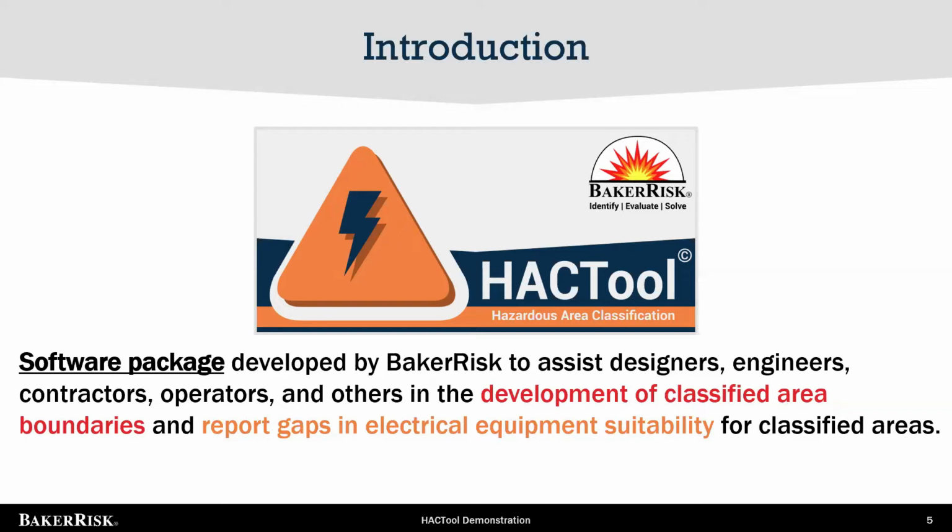And really, it was meant to assist designers, engineers, contractors, operators, consultants, really whoever needs to know about hazardous area classification, ignition sources out in the field, and purchasing equipment, and for the purpose of classifying areas, calculating the extent distance to our classified boundaries, determining what classification they are, Class 1, Div 1, 2, Group A, B, C, D, etc. As well as it serves a purpose of reporting gaps in electrical equipment suitability for classified areas.